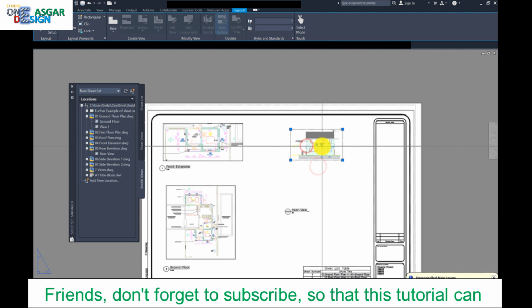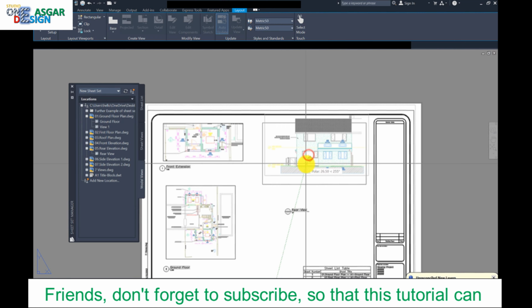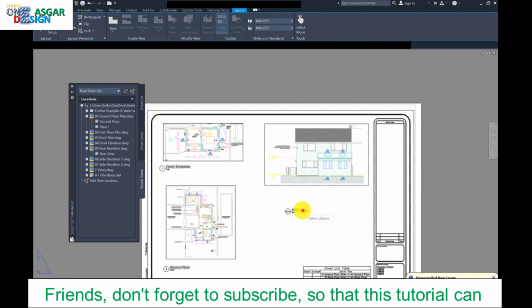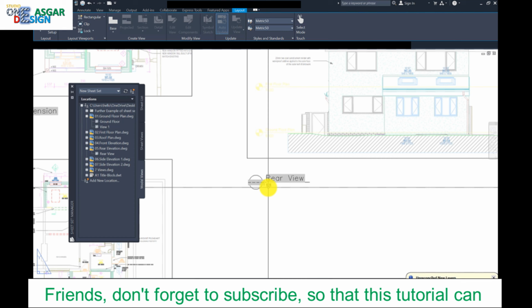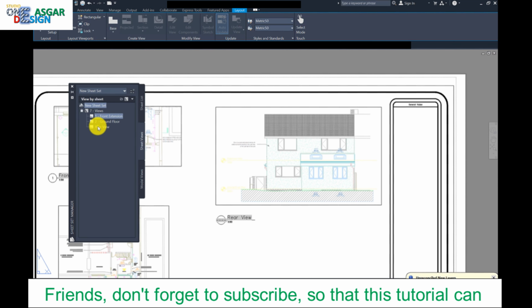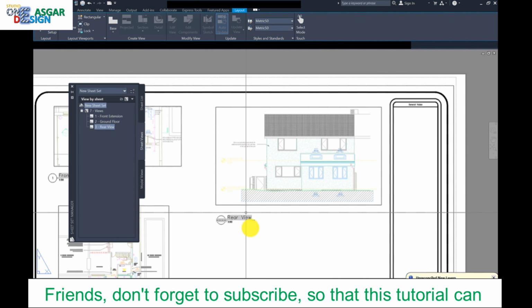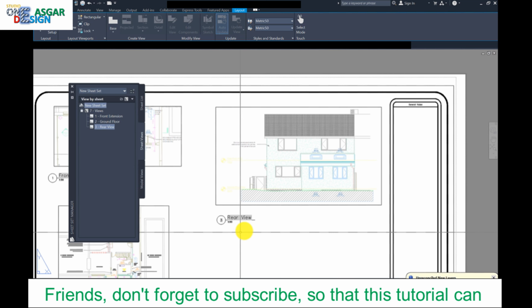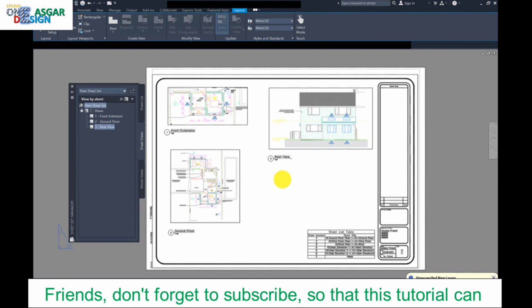What we might actually do is increase that up to 1:50. We'll move our title as well. Still reading 1:1, so we'll just regen that. We'll go to our sheet views, right click the rear view, rename and renumber, and this view will be view 3. Press OK. Regen. So now we can just reposition our titles.